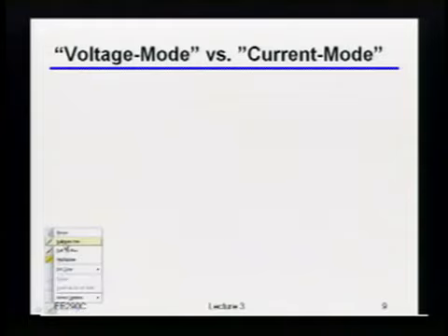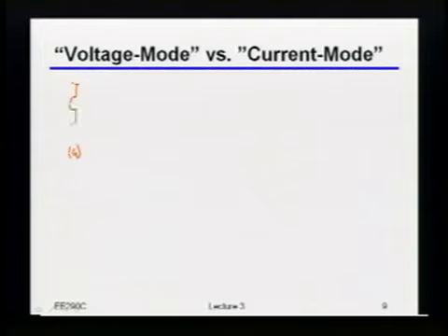Okay? So the first kind of driver is, of course, the thing that I've been harping on as being really bad for a while. But it actually turns out if we do things right, maybe it's not so bad. It is basically just, again, this good old inverter. And in this case, I'm going to say that inverter is just running off of some power supply I'm going to call VTT, meaning it could be separate from the supply of the rest of the chip.